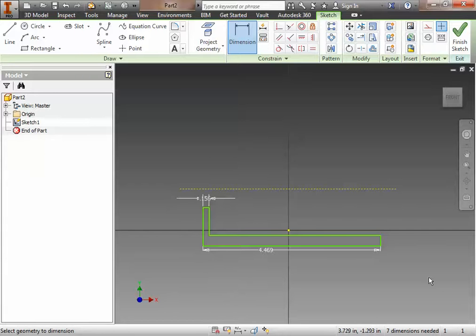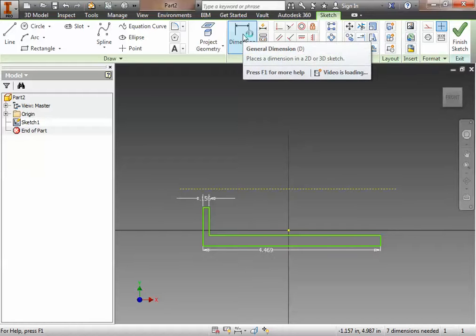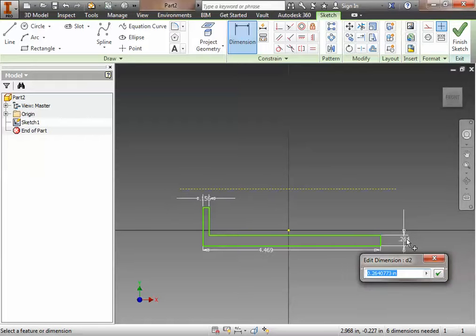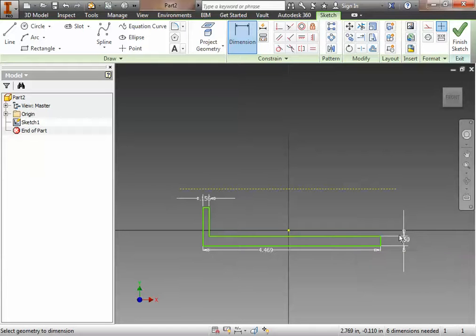Also, don't get scared when you add in these other three dimensions that it wants you to fill in. It is only using a thousandths precision, so don't worry about that when it cuts off if you insert more than a thousandths worth of things. So anyway, the first dimension it wants us to put in is the thickness of the handle, and it gives us a blank on the document for that. But if you look up at the drawing, in the top portion, it tells you how thick it is on the section view, and it's 0.25. So we put in 0.25 for the thickness.